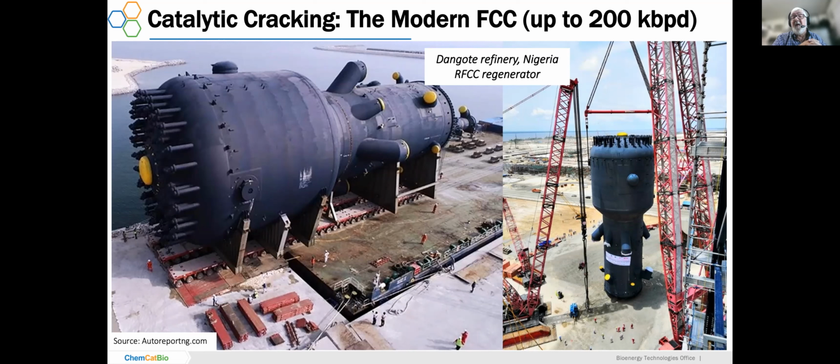The narrow part at the bottom is where the bubbling bed is occurring, so where the catalyst is, the coke is being combusted, and the big expanded region at the top is the freeboard or the disengagement zone, and you see all of the close-coupled cyclones emanating or sticking out of the top of that big beast. So I thought that was a real eye-popping way to bring that message home about just how big FCC is in today's modern world.